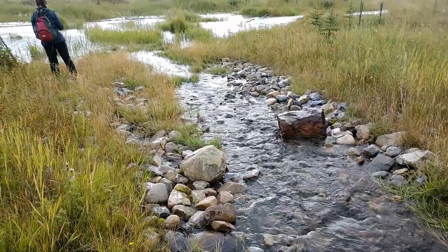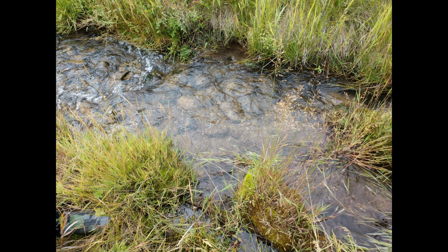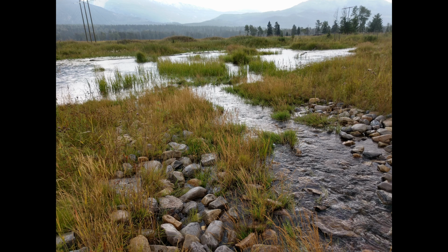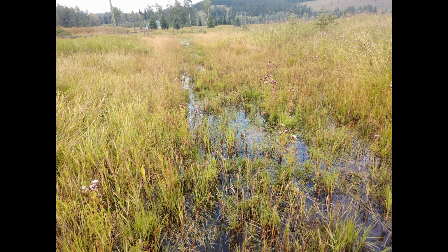Here's what one of the spillways looks like 6 years after construction. The rock we embedded in the spillways is working to control erosion. Water is flowing into and out from the wetlands in a sheet-like pattern just as designed. The spillways built on slopes that are less than 2% are supporting a diversity of sedges and rushes. You're not able to see the rock in the spillways where we were able to push it into the ground.